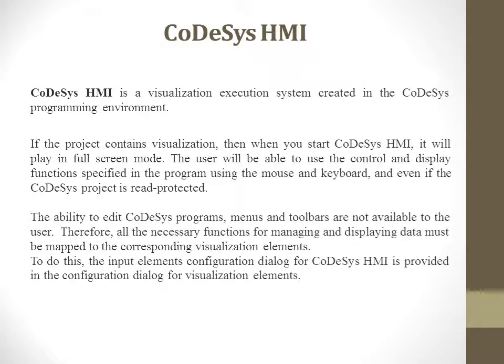So the ability to edit Codesys programs, menus and toolbars are not available to the user in this system. Therefore, all the necessary functions for managing and displaying data must be mapped to the corresponding visualization elements. To do this, the input elements configuration dialog for Codesys HMI is provided in the configuration dialog for visualization elements.